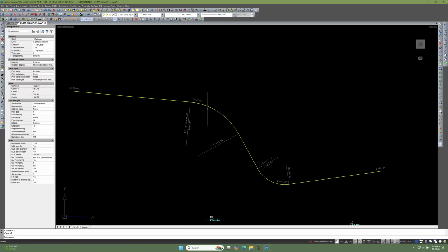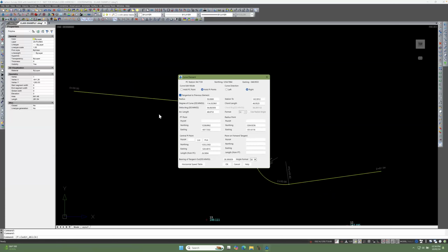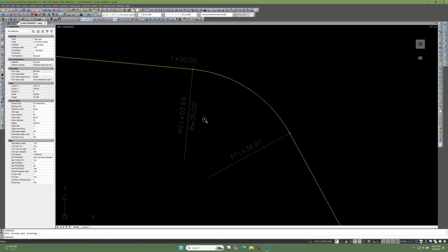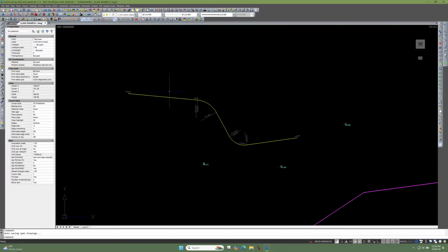Now, double click this again, double click my curve. Let's make that say a 35-footer. Save, exit. Now, did you see what happened? It re-annotated and it used the settings that I had in place the first time I did it. So that edit that I made was lost because it recreated it.